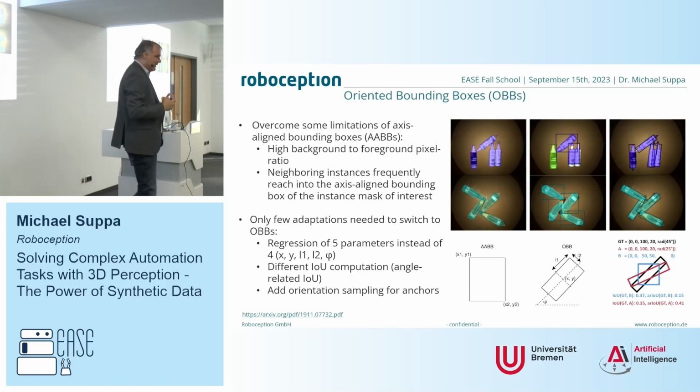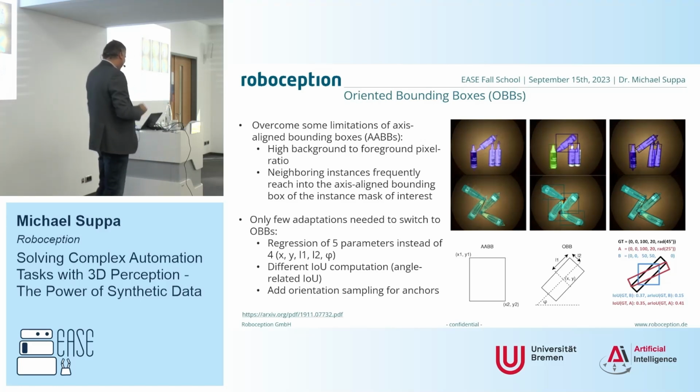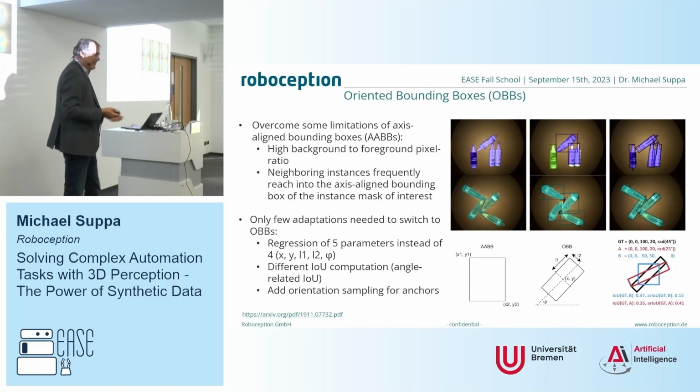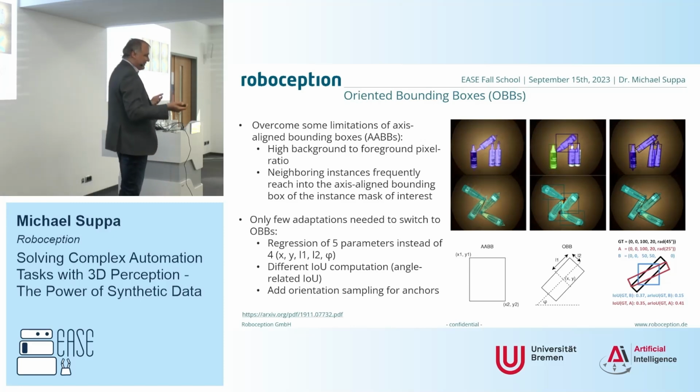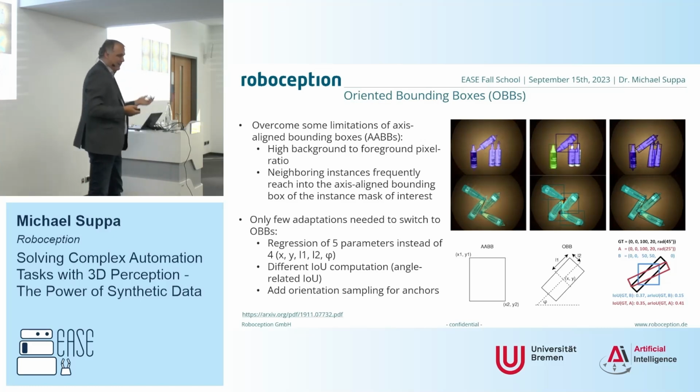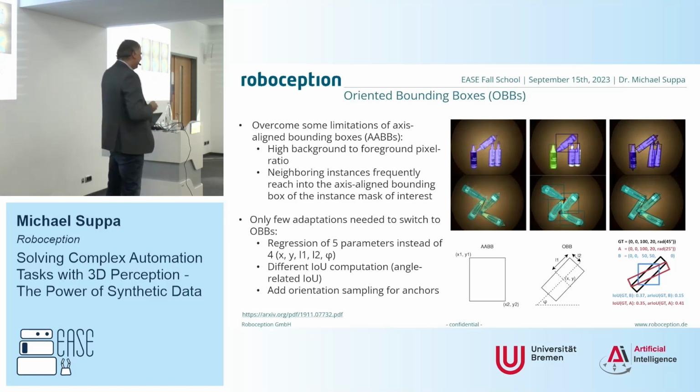So the customer says, "Hey, this is the most simple part I have," and you're telling him, "Hey, with my bounding box detector, that's actually a problem." Then they don't understand why the simple part may have issues with the bounding box detector. They look at a simple part and think, you should be able to pick it, no worries, right? This is why most of the time the simple parts are the problematic ones, because they don't have enough features, they're pretty roundish, and so on.